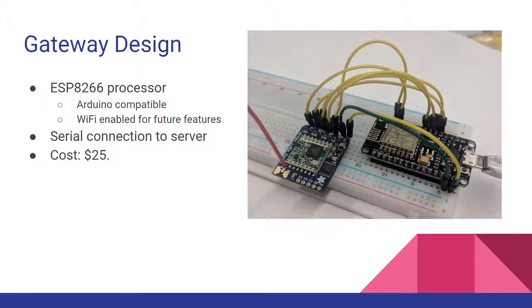And there's some Arduino code. The gateway firmware.ino in the repository is what's running on this chip, and it's pretty straightforward. I mean, the circuit's not complicated. It's a direct SPI connection. There's a reset pin. There's an onboard voltage regulator.